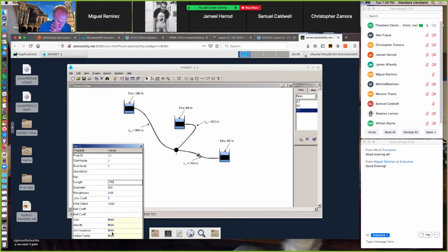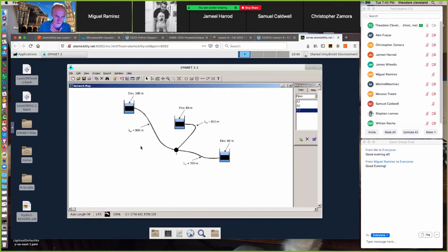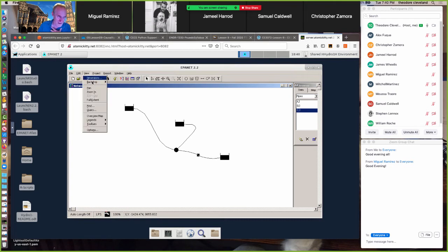You notice down here, this yellow area, we have the pound NA because we haven't made any calculations yet. Those are all calculated values. So that's the convention that the program uses to identify input versus a calculated value. So I can close the dialog box. I can close the backdrop, verify that the connectivity looks right, looks good to me. I'll put the backdrop back on.